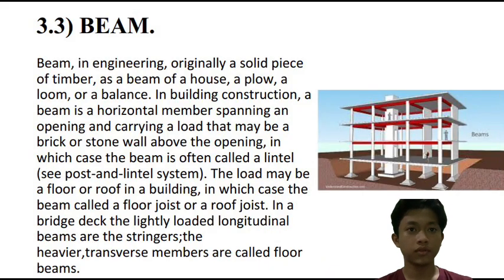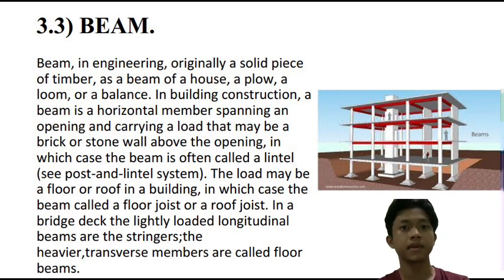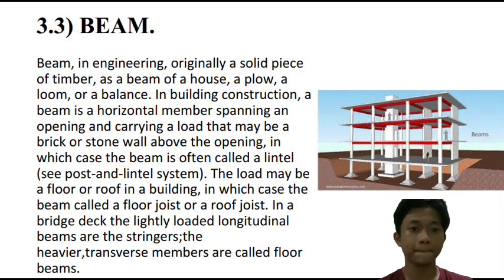Okay, so for beam: in building construction, a beam is a horizontal member spanning an opening and carrying a load that may be a brick or stone wall above the opening, in which case the beam is often called a lintel. The load may be a floor or roof in a building, in which case the beam is called a floor joist or a roof joist.